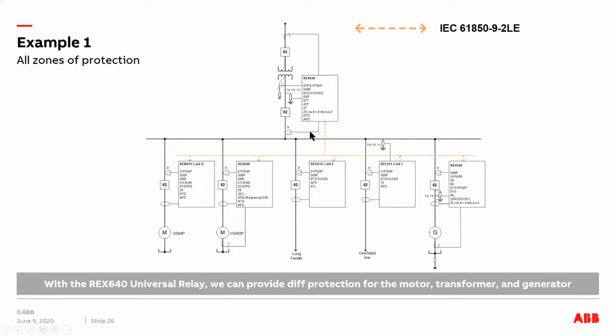So you can have, from one side, a traditional CT, and on the other side a sensor input, which typically comes from the medium voltage switchgear, and then you can achieve the differential protection based on that. Okay, so that is possible, and then the voltage inputs are taken from the voltage sensors.